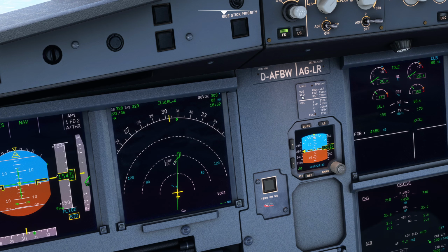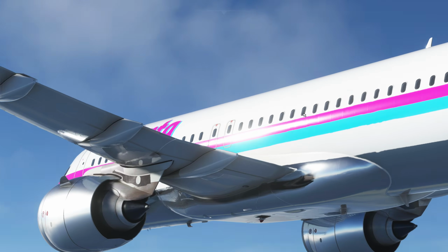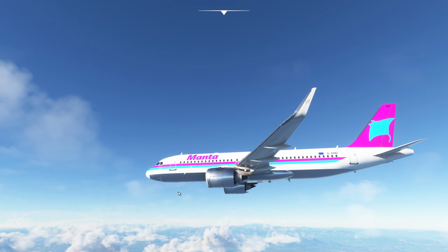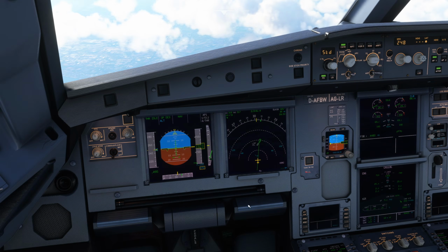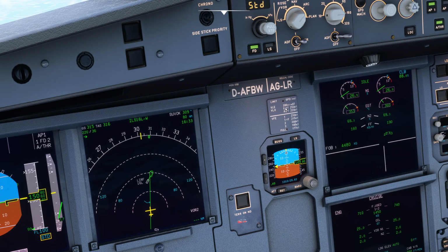But we're actually more limited by this one, VLO, velocity of landing gear operation. We can extend the landing gear at 250 knots, and we can retract it at 220 knots. So you can be faster when you lower the landing gear, because of course the nose gear is going to drop out of the nose and go into the airflow, so the airflow will help it lower the right way. But the retraction means it has to go against the airflow, hence 220 knots is the maximum at lower speed. The velocity with it extended is 280, Mach decimal 67. You can go faster once the gear is out, because once the gear doors are closed, it's then safe to accelerate the aircraft.